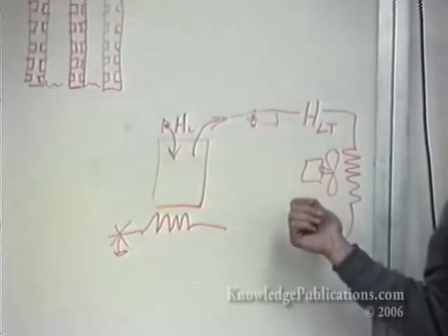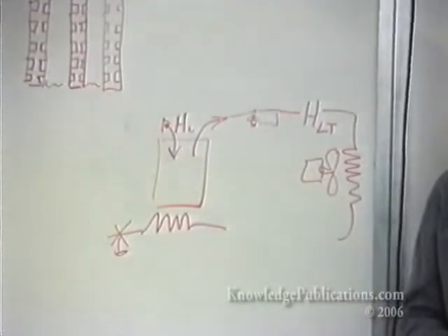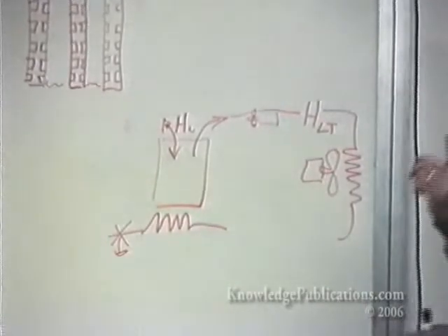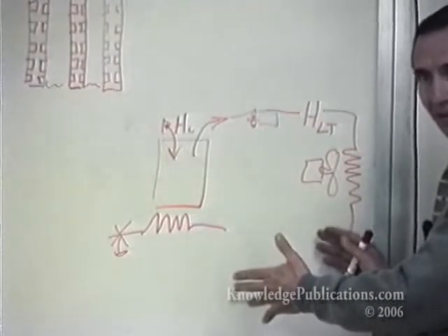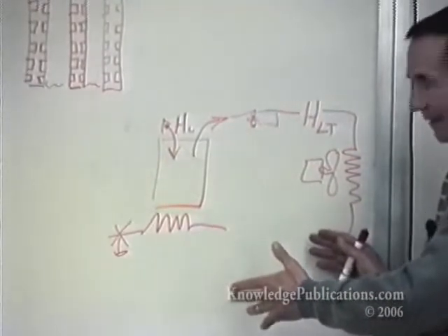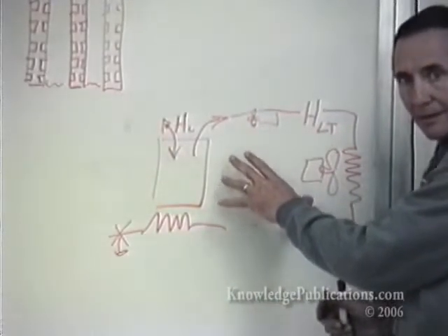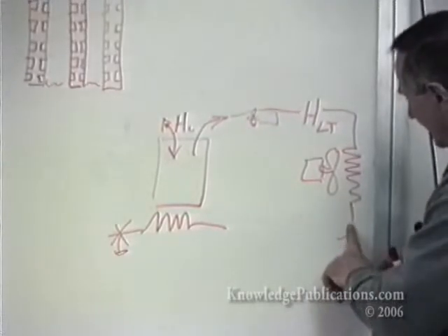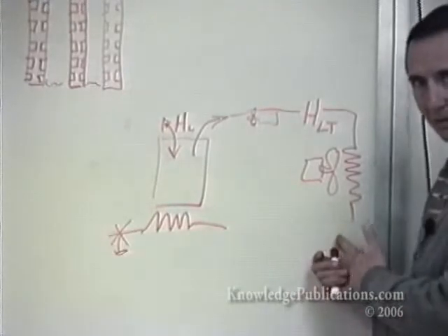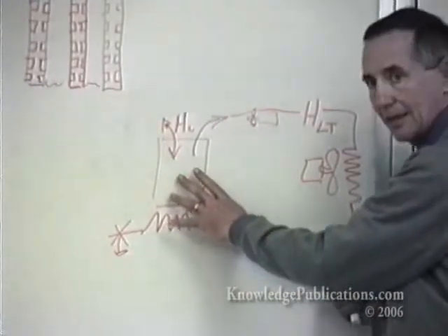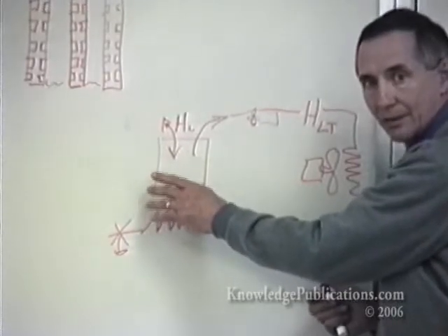Do you know how much cooling we do in a normal passenger vehicle? Big time. You have no latent heat of vaporization problem. That's true. This one has no latent heat to deal with. This one isn't like expanding Freon. This is a direct gas cycle. So then the hydrogen comes back, you just let it expand and you let it reabsorb back into the container? You can, yeah, well, this hydrogen now goes to an alternate cell, an alternate hydride, which is in the out of phase condition of this one.